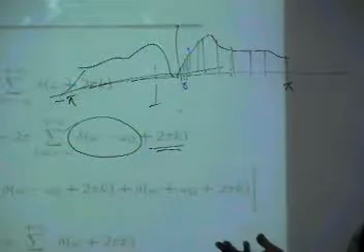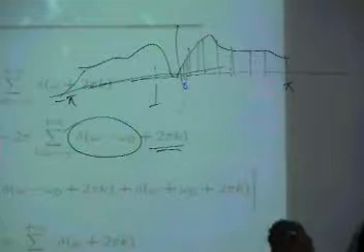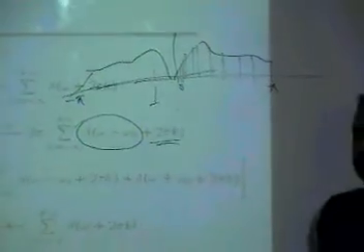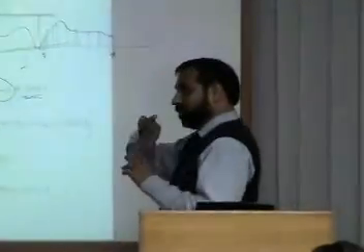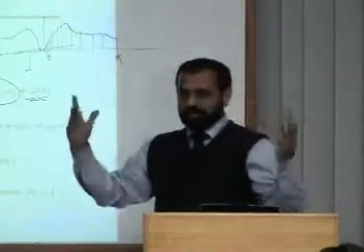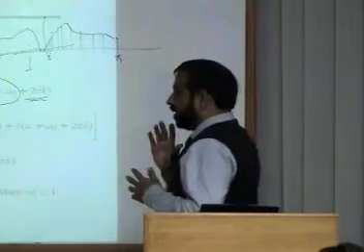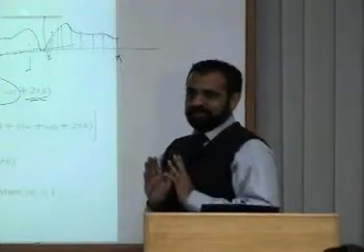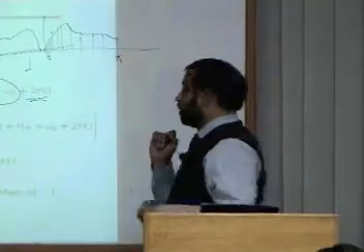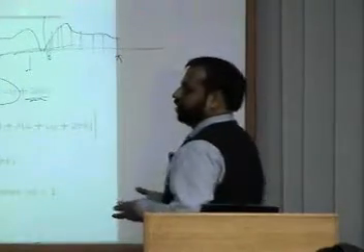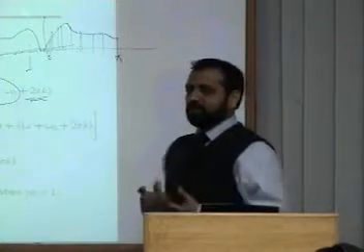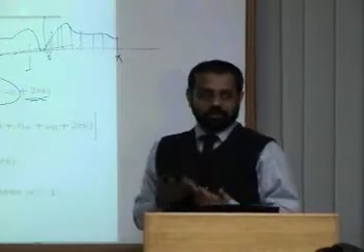And that's what the Fourier transform is. It only tells you how many complex exponentials are there in the signal, and that is what frequency is. Looking at this, I know these are the complex exponentials. If they appear on both sides, these are the cosines. So I say these are the frequencies in the signal, and this is an interpretation. Why? Because Fourier concluded that this is really true. Though it's a mathematical formula, it tells you something about the frequency contents in the signal.